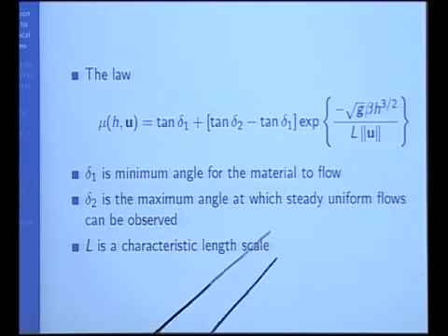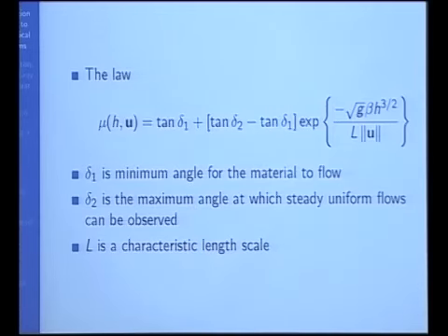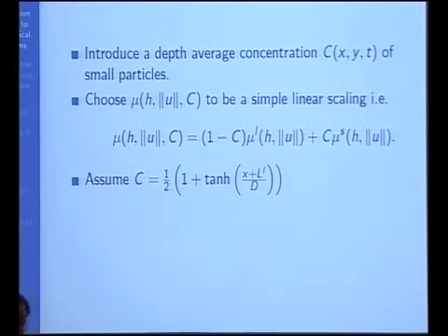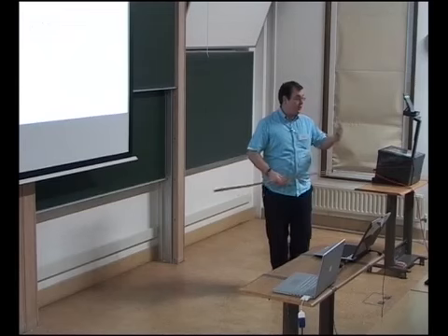I think this also has been presented a few times. This is the friction law which was experimentally determined, described by Olivier Pouliquen for granular materials. It has two angles, the minimum flow angle and the maximum flow angle. It was experimentally derived, and it is very powerful, and it can predict all sorts of things on flows, including the correct front shape for flows. So it's a first step towards introducing the proper rheology to granular materials. So we'll be using that.